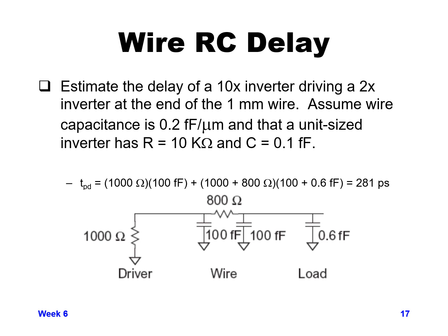You can see if we didn't have that long wire there, and we just had the driver driving the load and figured out the RC time constant for that, it would come out to just 0.6 picoseconds. So obviously 99.9% of our delay here is exclusively due to the long metal wire. So wire delays can have a very dominant effect if you have very long wires, much more so than just the load gate that you have on a given driver.